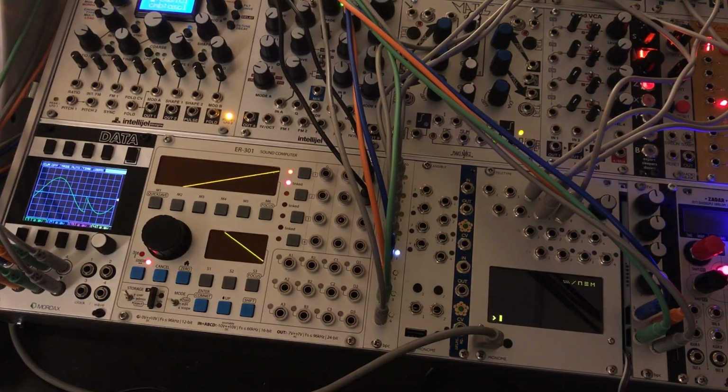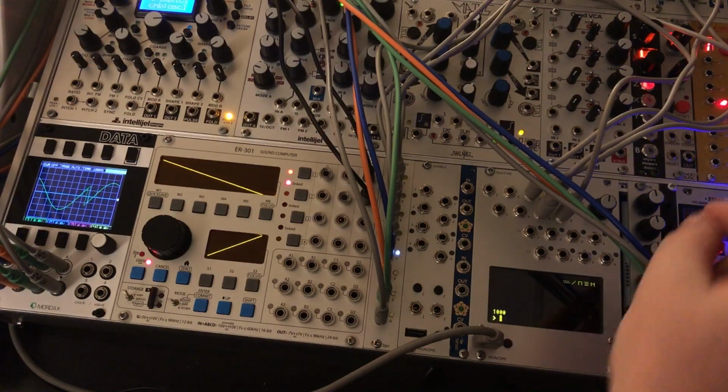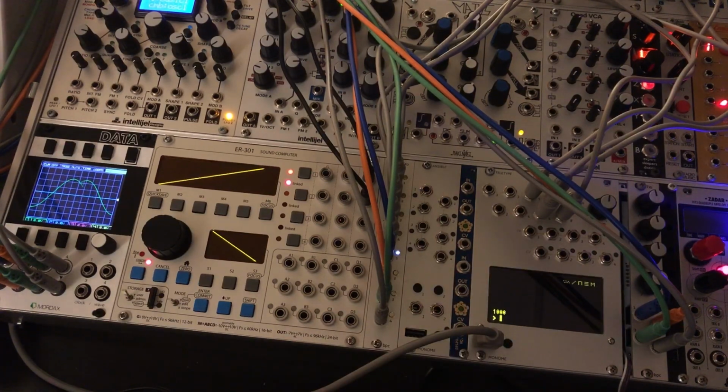So let's set up some of these things into a script. We'll put some of these in the metronome script to start. Right now, if I type M, metronome is running pretty slowly. It's just running at 1,000 milliseconds or every second. That's way too slow. I don't want there to be 1 second intervals between when I turn the parameter knob and when it reads the value. So let's speed that up a lot. Let's set metronome to 25, and now it'll fire 40 times per second, and that should give me a pretty smooth change on these.